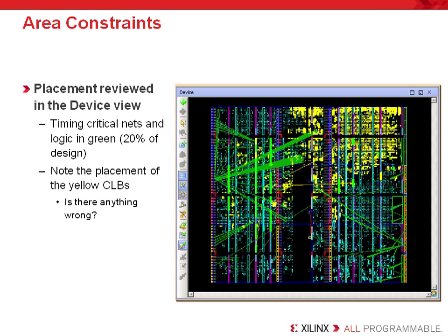As we work further through the timing closure flow diagram that I described earlier, we have pretty much used all the easy solutions to gaining timing closure. Now, if we need more speed, we'll have to get into making area constraints with Plan Ahead, which is actually not that hard, but the key is having your code fixed.